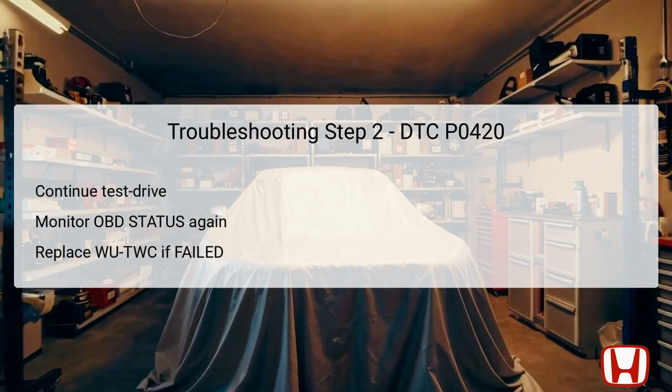Continuing from the first step, it is imperative to conduct a comprehensive test drive until a definitive result for DTC P0420 appears on the HDS. This phase involves maintaining specified speed and throttle conditions that help simulate real-world driving scenarios. During this test drive, it is essential to continuously monitor the OBD status for any indication of the DTC.